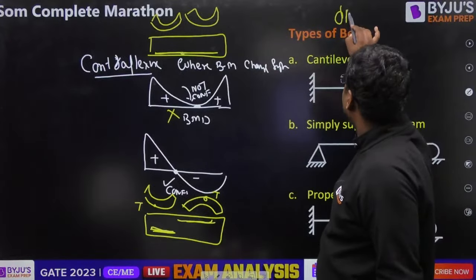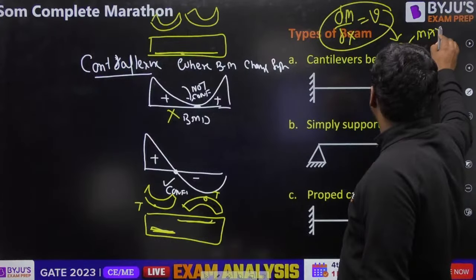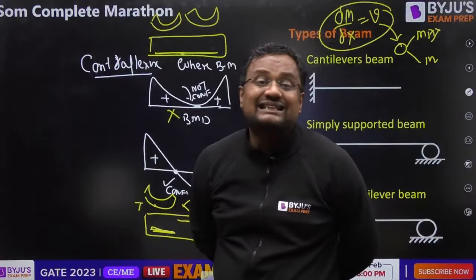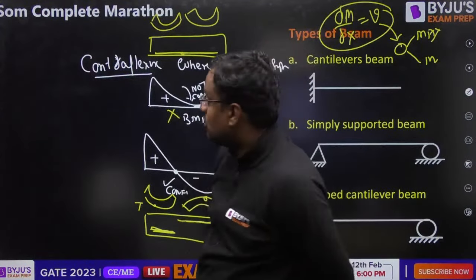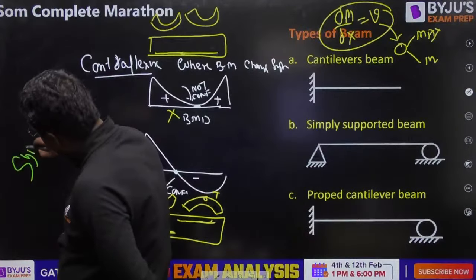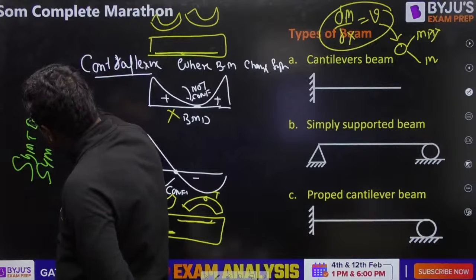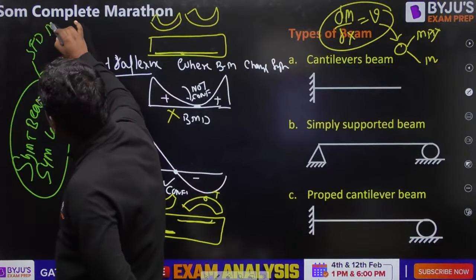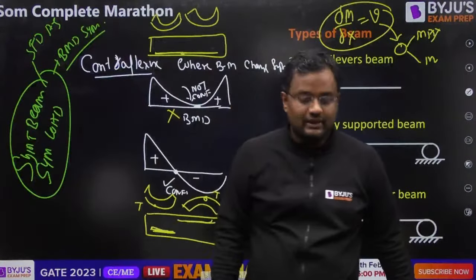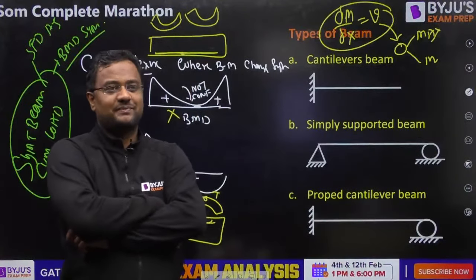And since the slope of bending moment is shear force, wherever shear force is 0, bending moment is either maxima or minima. If dy by dx is equal to 0, at that point the function value is either maxima or minima. And one more point: for a symmetric beam and symmetric loading, SFD is anti-symmetrical and BMD is symmetrical. Understood this? Please tell me in the comment section.